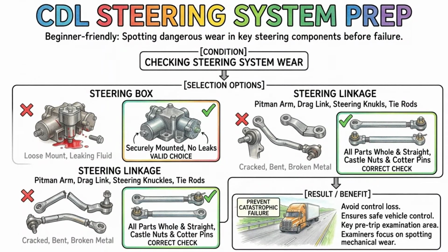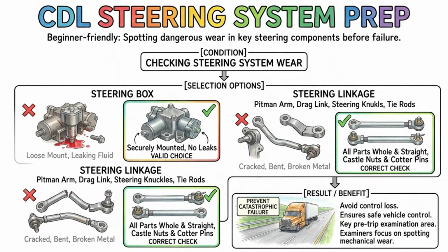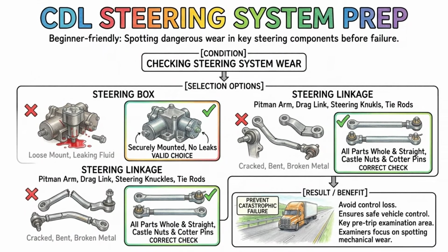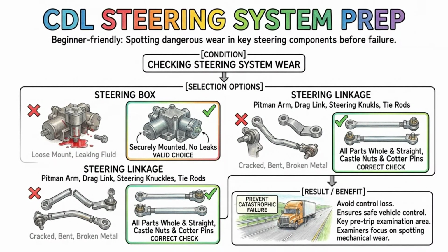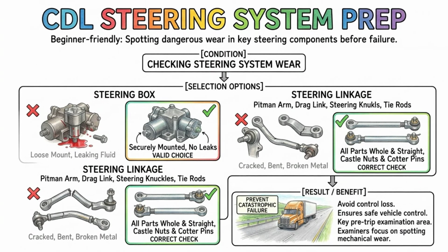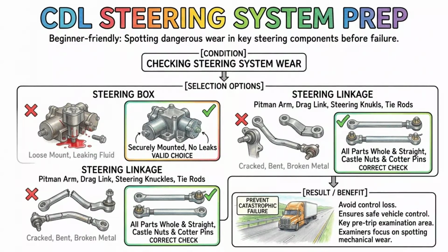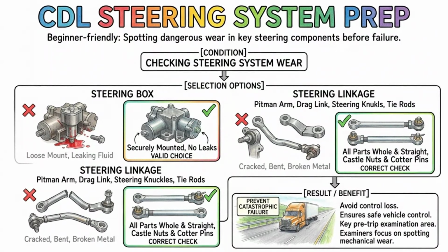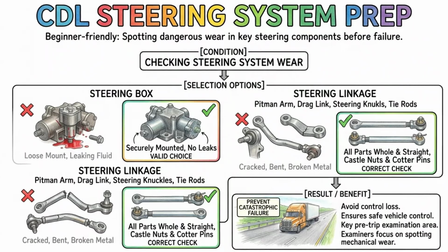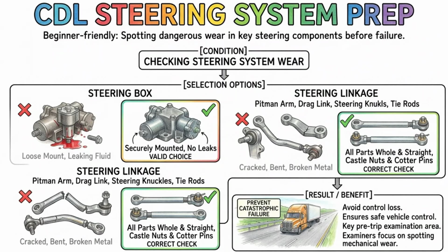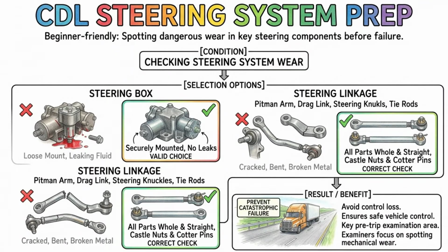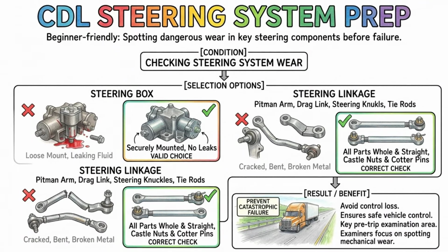Communicating your intentions to other drivers is a core principle of commercial driving safety. You should activate your turn signal at least 100 feet before making a turn or changing lanes in city traffic. On the highway, it is best practice to signal much earlier to give fast-moving traffic plenty of time to react to your large vehicle. Additionally, you should leave your signal on until you have completely finished your maneuver. The exam will test your understanding of proper signaling distances because sudden moves in a massive truck often lead to tragic accidents.